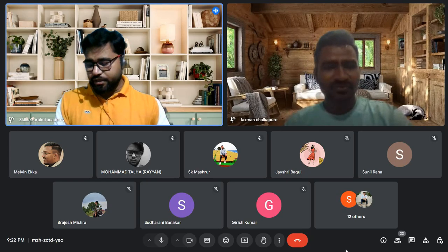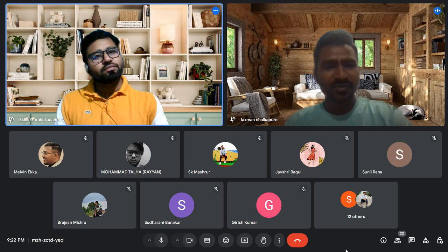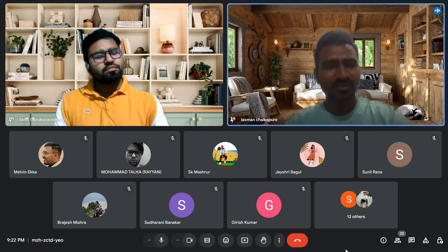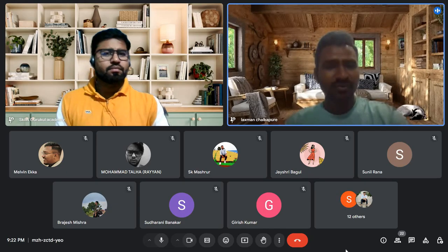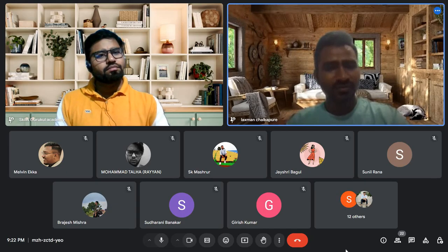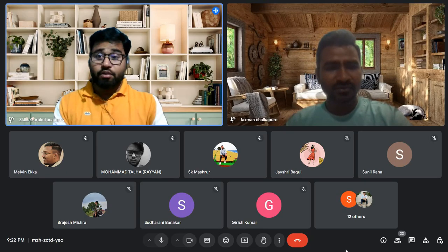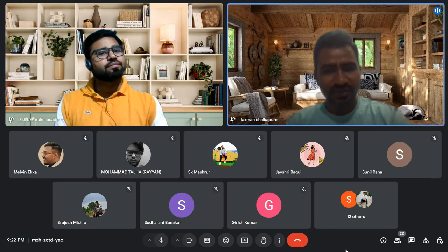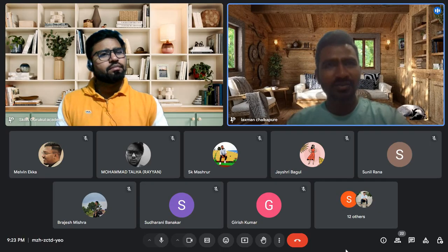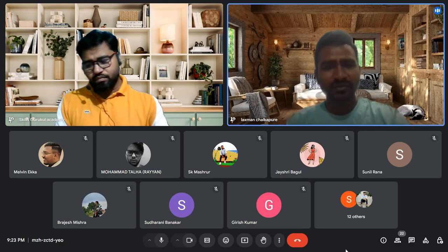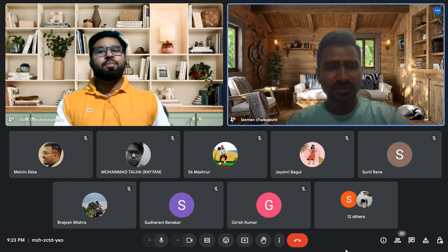Okay. And what is BIM? BIM is building information modeling, and it's a very intelligent model. We can extract information from it for further construction. How to find BVS from Revit structure? Yes, we can surely find BVS in scheduling, and we can find scheduling in the View tab, Create, and then Schedule and Quantities. Good. What is the standard A4 paper size?